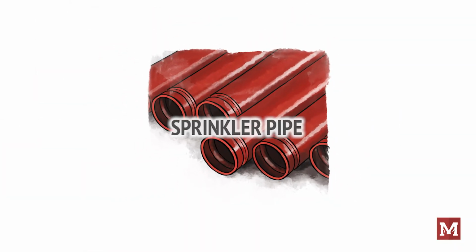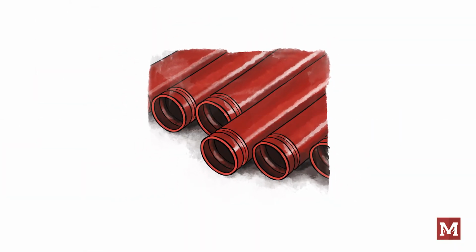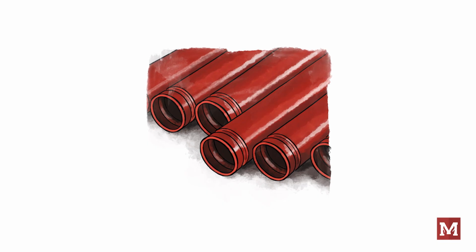Sprinkler pipe. Another factor in getting ready to calculate a system is identifying the sprinkler pipe. If you're designing the system from scratch, you probably have this covered. But if you're reverse engineering the system, you need to know this. If the system is using metallic pipe like black steel, you need to know the schedule of pipe. Like we touched upon in the first segment, Schedule 7, Schedule 10, and Schedule 40 metal pipe are very common.